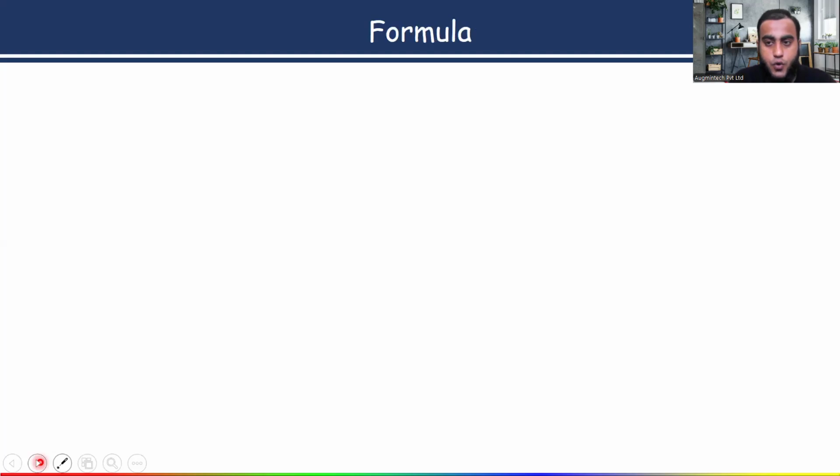Clear? I hope all of you understood our criteria, how you get the fan capacity, and why we are calculating the external static pressure. Now here some formulas are there. As I told you, external static pressure is caused by the ductwork. Let's say you have the longest duct route and you are calculating the external static pressure.